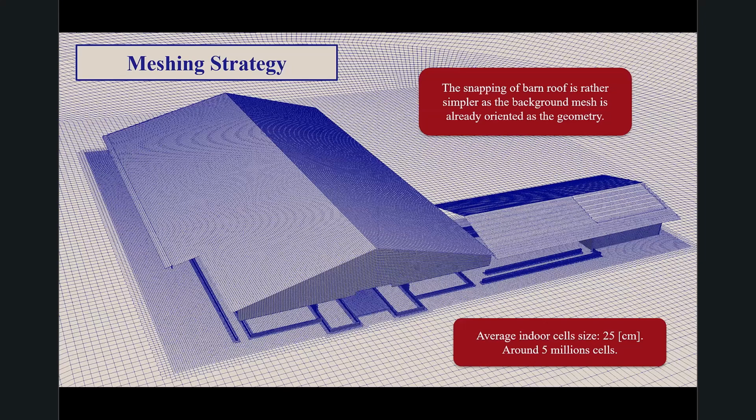The optimal value was actually a bit higher for the height of the simulation in the case of natural convection, because in that case we do have buoyancy-driven flows that flow up to the top of the domain, and this did create quite a lot of problems if the flow was not fully developed by the time it reached the top, of course. Okay.